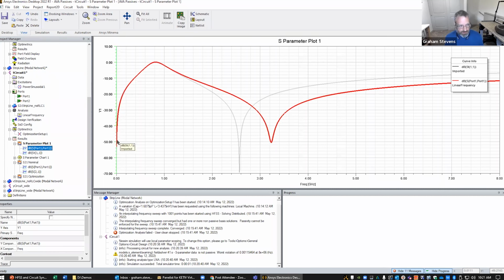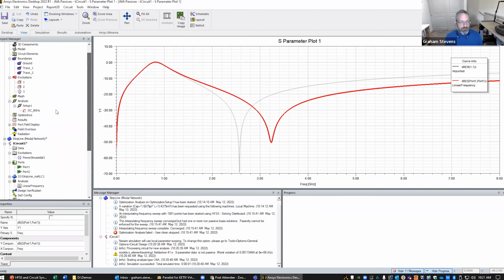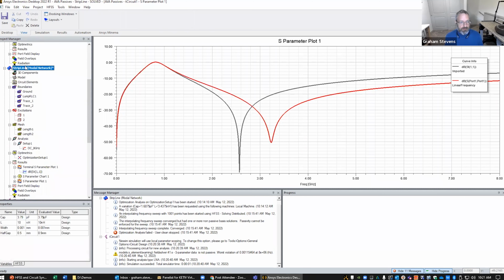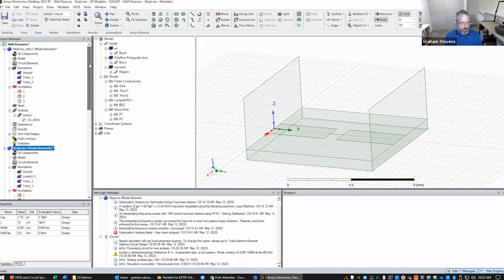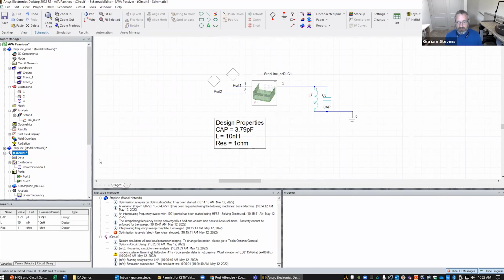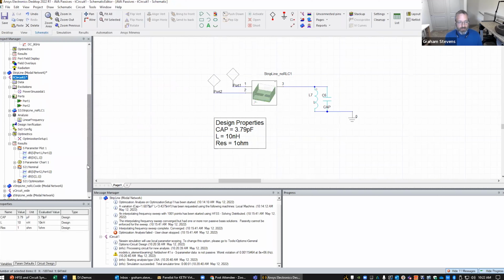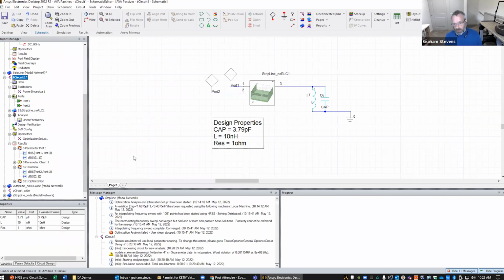And the reason for that is what I was saying before. When I look at the port versus when I change this RLC boundary to a port, they are slightly different, and they do resonate differently at higher frequencies. And so you may have to go to a less of an approximation than what we're using right now.